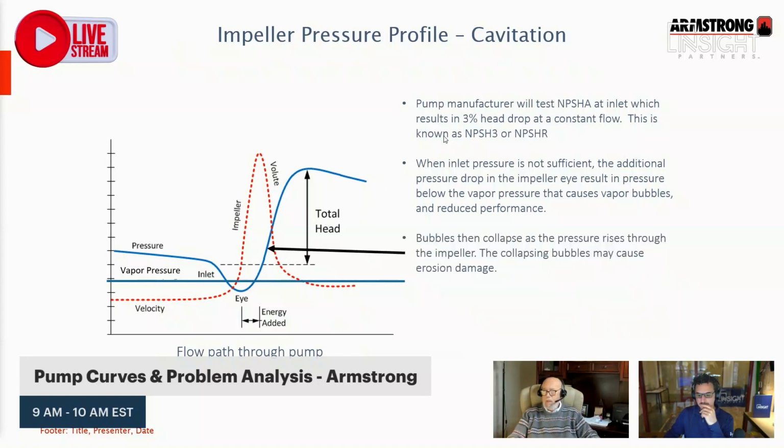And then as those bubbles collapse and the pressure rises through the impeller, the bubbles cause erosion damage inside the casing. They will erode things. I'm going to show you a picture here in a minute of what happens.